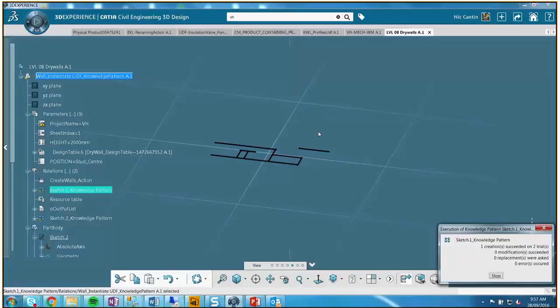And the nice thing about this, that I guess we're not going to have time for, is the next iteration. Reusing these lines for each of the stud walls, because the stud walls are linked to the center line, we actually reuse the center line for all of our MEP. So we'll locate a node or a point on that stud wall and type that for a specific riser.